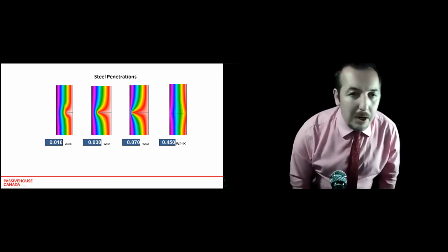The case when you have steel going from outside towards inside is a lot more damaging, because you're dragging your heat out of your building, causing cold and potentially moisture problems. So I just wanted to touch on that before I go ahead with this slide.